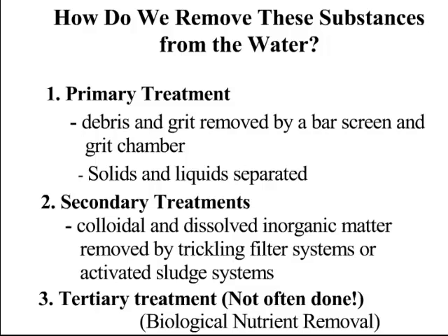Primary treatment is separating solids and liquids. So primary treatment is going to involve a series of bar screens that separate out all the trash and junk that gets flushed down sinks, that gets washed into our gutters. So if you've put potato peel down the sink, or you've flushed a tampon or flushed a condom, then it's going to remove that from the sewage right at the beginning.